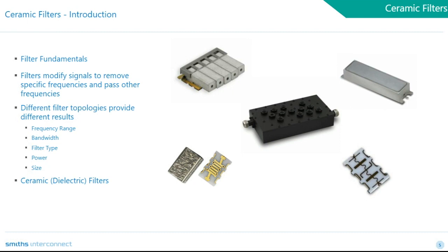There are many factors to consider when choosing the appropriate RF filter for an application. The frequency range, fractional bandwidth, the filter transitions from the pass band to the stop band, and the power level of the signal are some of the variables to consider. Additionally, the performance of the filter, the loss of the passband and the amount of rejection, the size and cost are other variables. Often, the filter selection will balance the trade-offs with smaller size and weight and the filter performance.